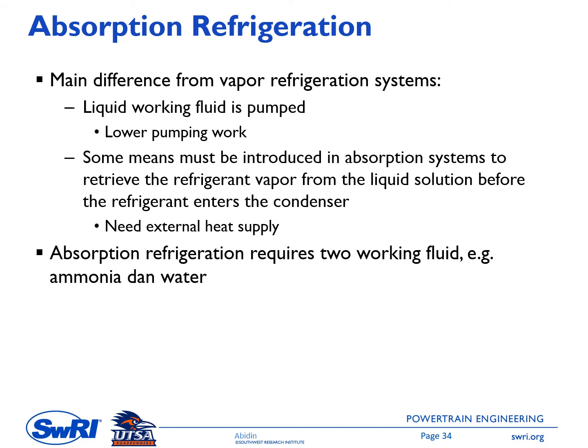So absorption refrigeration also requires two working fluids. For example, ammonia and water, or maybe water and lithium bromide. In a standard vapor compression refrigeration system, we only need one working fluid. In this absorption refrigeration system, we need two working fluids.